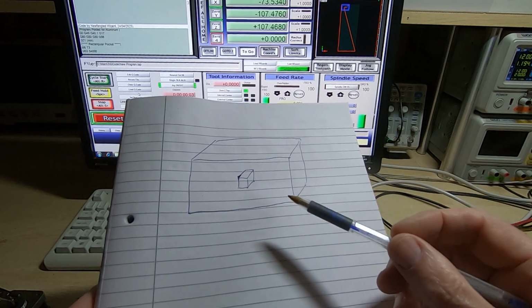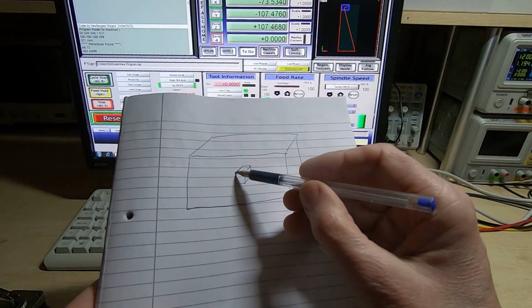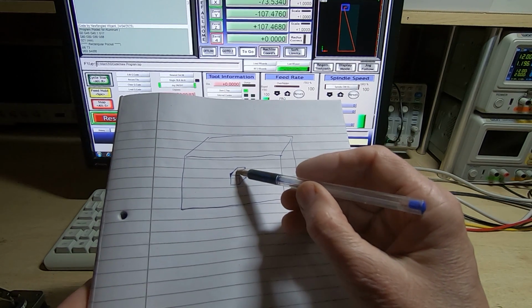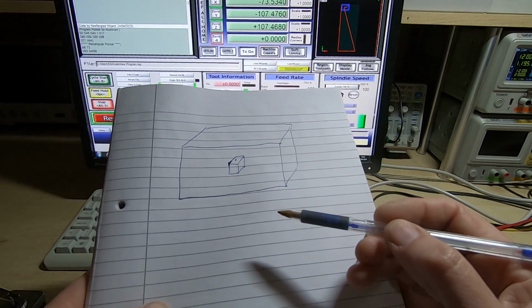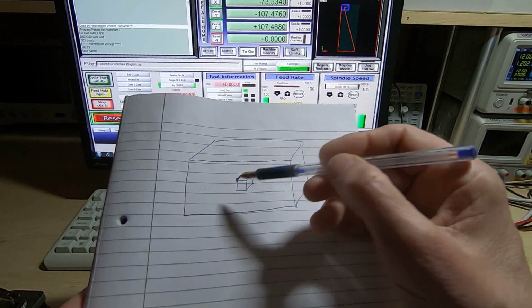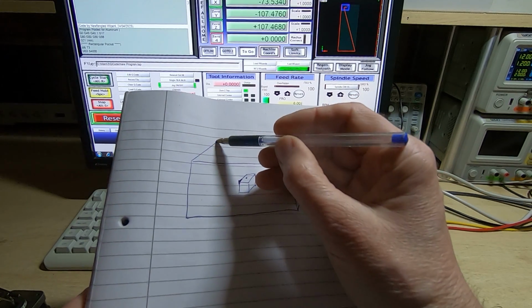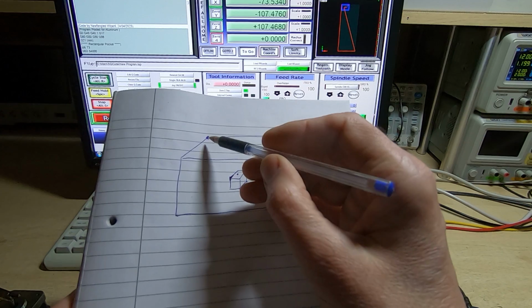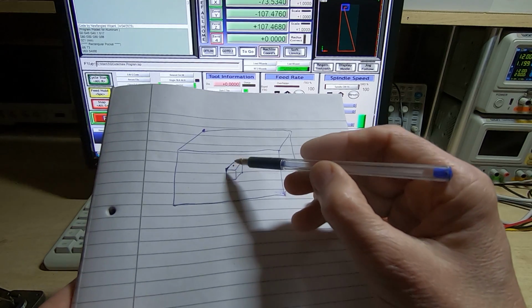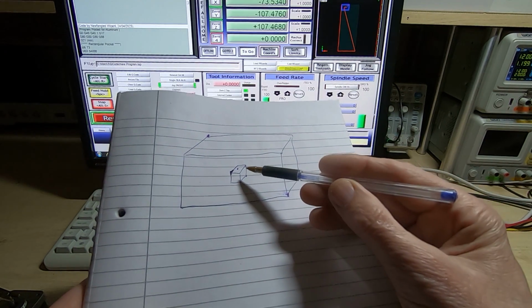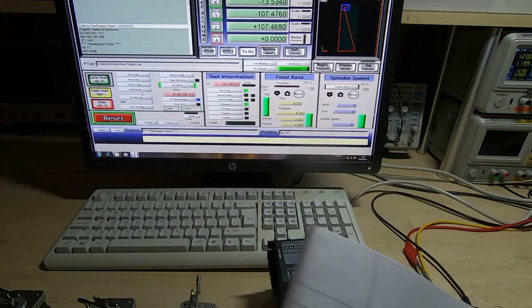So if we have a milling operation, a CNC G-code file, then it generally will be referenced to a position close to the stock material that we're using, and we mill away the parts we don't want, of course. When we zero the mill, it returns to a home position for the X, Y and Z. So that might be up here somewhere, 0 for X, 0 for Y and 0 for Z. But we then need an offset to get to the actual part and the location within this 3D space that we want to use. And MACH3 uses what are called fixtures.